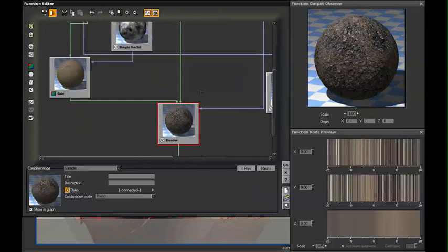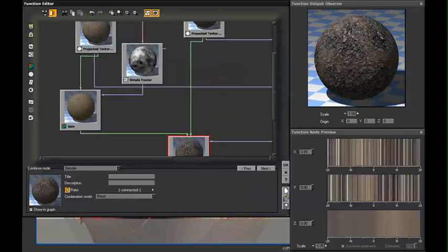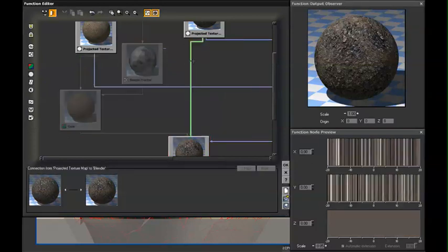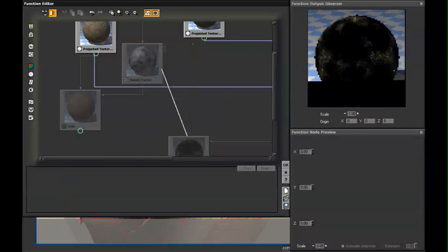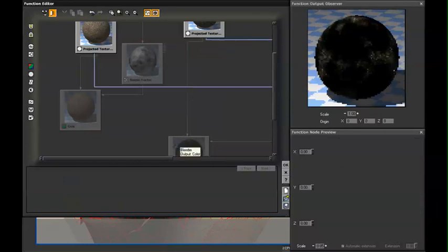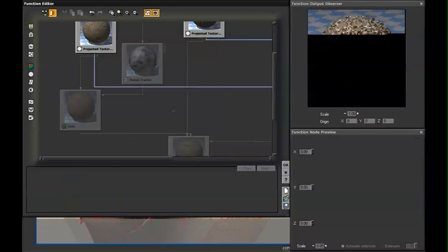Right now, if we take a look at our blenders, all we really need to do if we want to swap where we have right now the input 1 in these areas and then input 2 in these areas, we could swap those very easily if you wanted to change that out. Same thing if you were working with the slope where you decided you wanted the one material on top rather than on the bottom. We can easily change that out, and all you would need to do is just swap out these different links. And the best way to do that is just select a link, remove it, and then you can swap that over and then reconnect the other one.